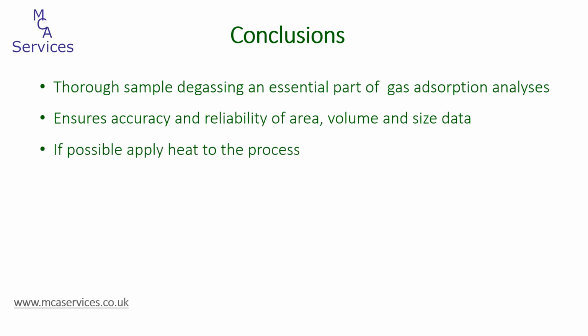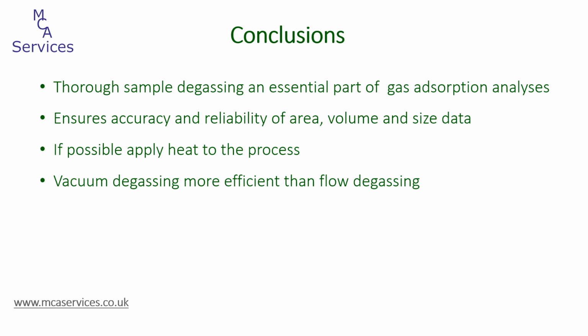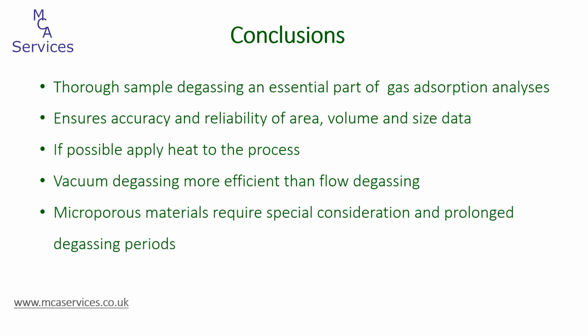Wherever possible, we should apply heat to the degassing process. Vacuum degassing offers higher efficiency than flow degassing in terms of the degassing period required. And for the analysis of microporous materials, special consideration when selecting appropriate conditions is required, as these often demand prolonged degassing times.